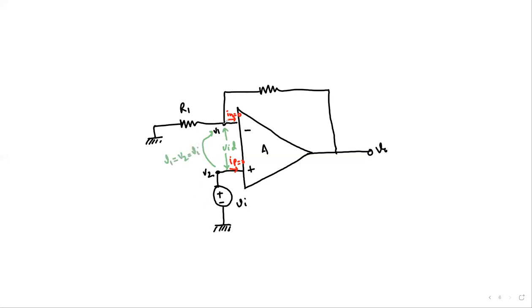Since Vi comes over here, the current that will flow through this resistor R1 is I1, and this is our resistor RF. The same current will flow through the resistor RF, so we can either call it I1 or define it as IF. These two currents can be equated, I1 equals IF, because one current is leaving the node and another is entering the node. So let's see how feedback works here and what is the use of feedback.